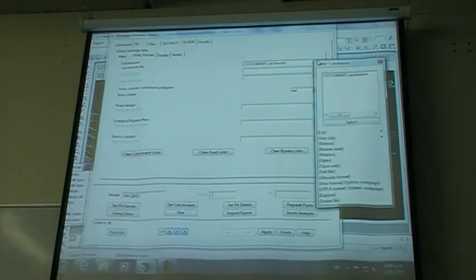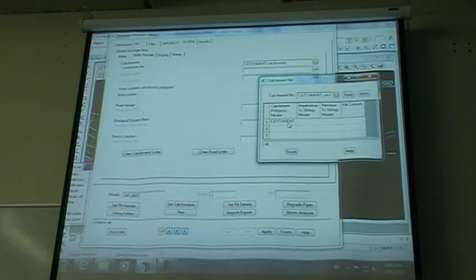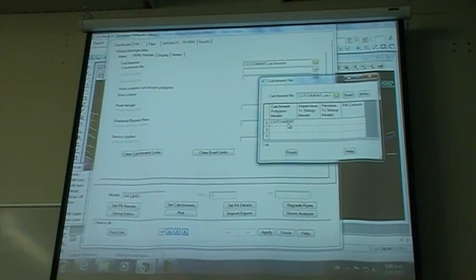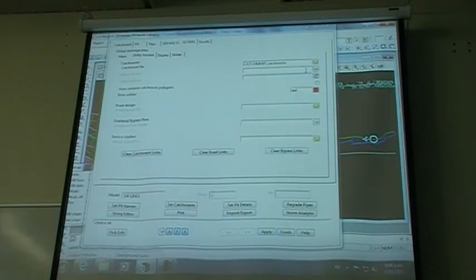And if I open that, you'll see all it's asking me for is a default polygons model that I'm going to draw my catchments into, okay? Whenever it runs the network editor, it's going to look for polygons in that model and assume that they are the catchment. All we're doing is telling it where to look. Did everyone manage to find where they'd saved that?